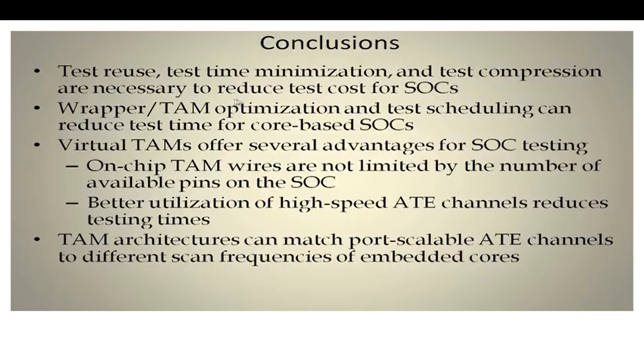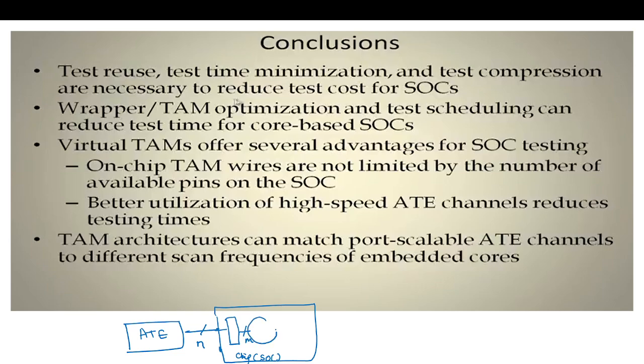In conclusion, I just want to say one thing. This is the ATE. A number of channels are coming, say N channels, which are applied to a chip, say a system on chip SoC, where we have a logic which converts to M bits. These M bits are applied to the core. Again, we get an M bit output. Again, we have a logic which converts to N bits, and again back to the ATE.